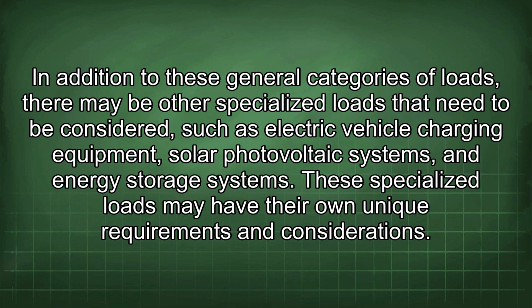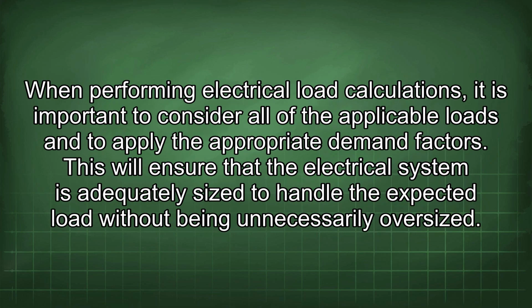In addition to these general categories of loads, there may be other specialized loads that need to be considered, such as electric vehicle charging equipment, solar photovoltaic systems, and energy storage systems. These specialized loads may have their own unique requirements and considerations. When performing electrical load calculations, it is important to consider all of the applicable loads and to apply the appropriate demand factors.